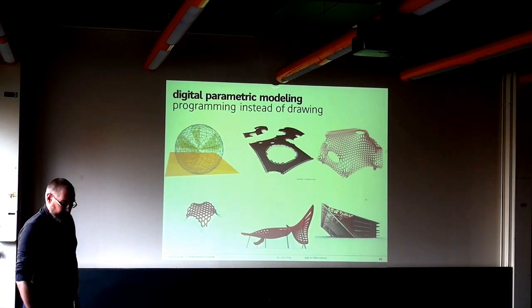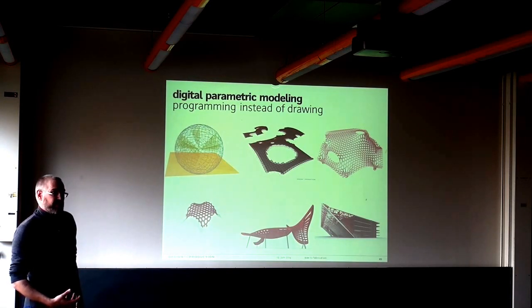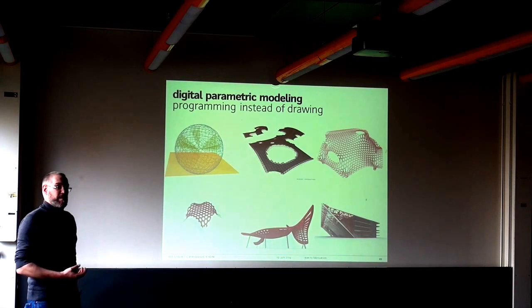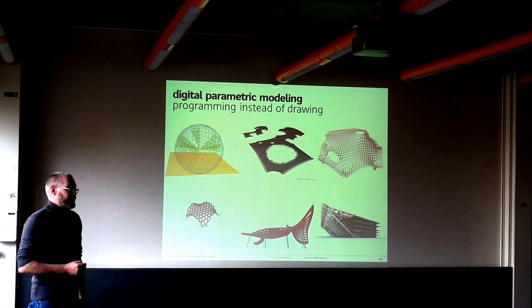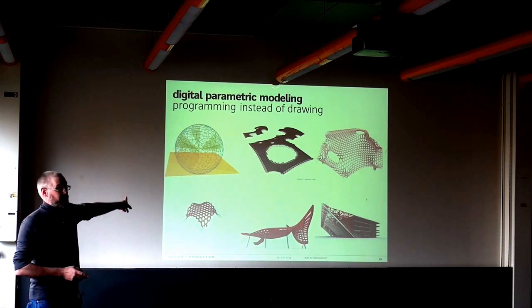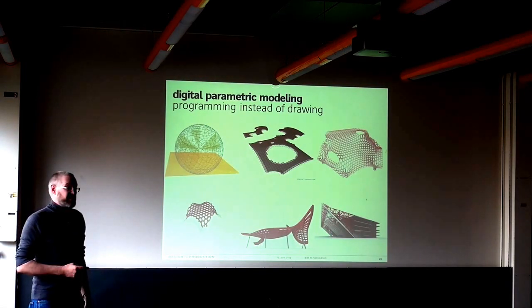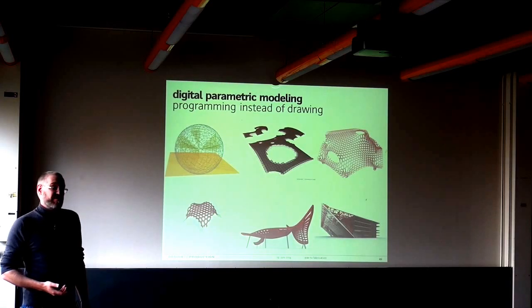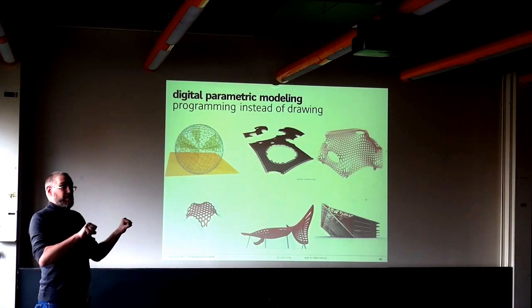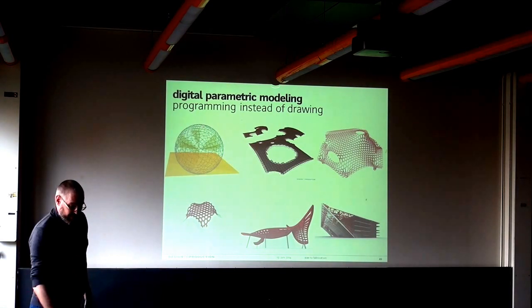And you end up at an information depth, at a detailing depth that is much more than the usual BIM things that you're handling. I mean, the BIM UK protocol says that the BIM model is roughly in the scale of a 1:50 drawing. We're working on 1:1 in the end, as every single node is detailed down 1:1 basically, and this is what you have to do if you really want to go into digital fabrication. This is the main gap between what BIM is now and what BIM has to be if you go down to fabrication in the end.